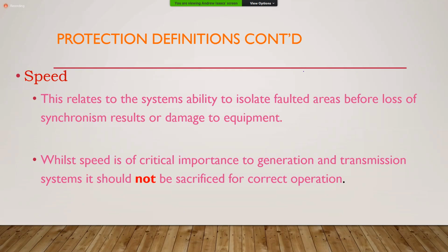Now, if you lose that load just like that, it's going to affect those generating units out by Rockford. And what I'm getting to is that the generator has what we call a critical clearing time, meaning that you must deal with this matter, whether it is to clear the fault or deal with the loss of load quickly.